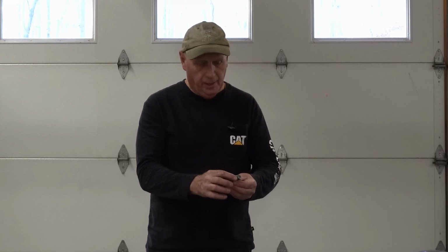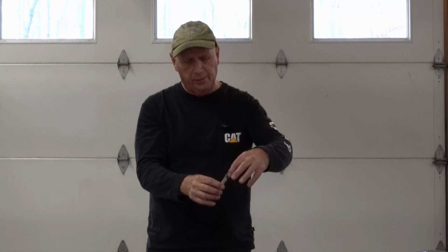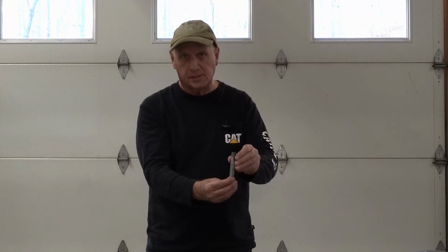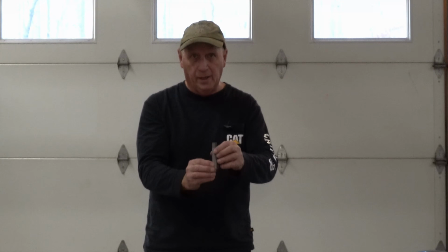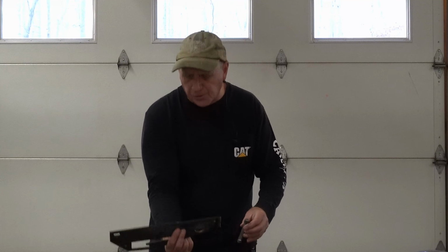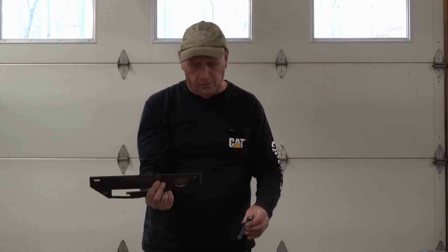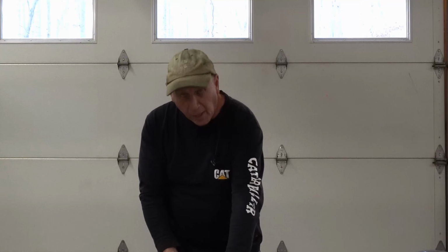Now that the pin is complete, I've got to make a disc that's going to go on the top of here, weld on the top, and it's going to have a 3/8 inch rod that's going to index these flats so we can make that 90 degree bend. So we're going to start laying it out. I've got a piece of 3/16 inch mild steel. That's going to be plenty thick enough for what this needs to be. You could probably make it a lot thinner than that because it's not really going to be supporting anything.